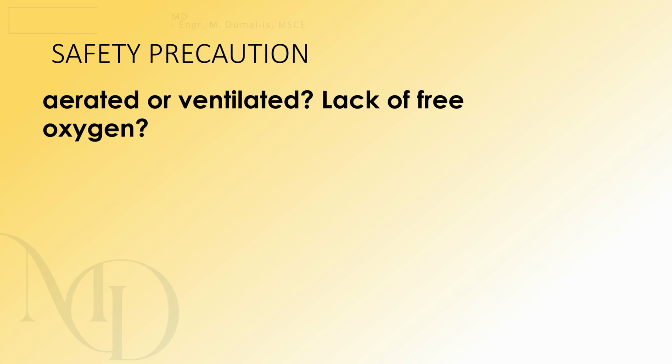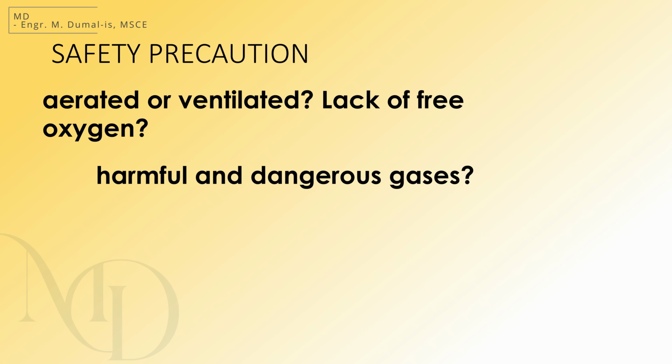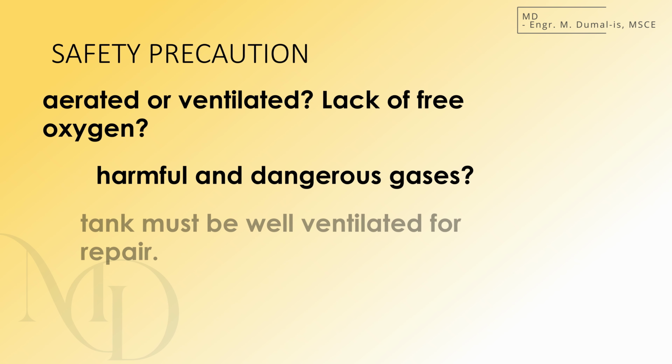In most cases, septic tanks are poorly aerated or ventilated. They lack free oxygen. Under this condition, a person who enters the tank for repairs or cleaning may face almost instant death. This is because septic tanks may contain harmful and dangerous gases. That is why, before any repair work or cleaning is carried out, the tank must be properly ventilated.